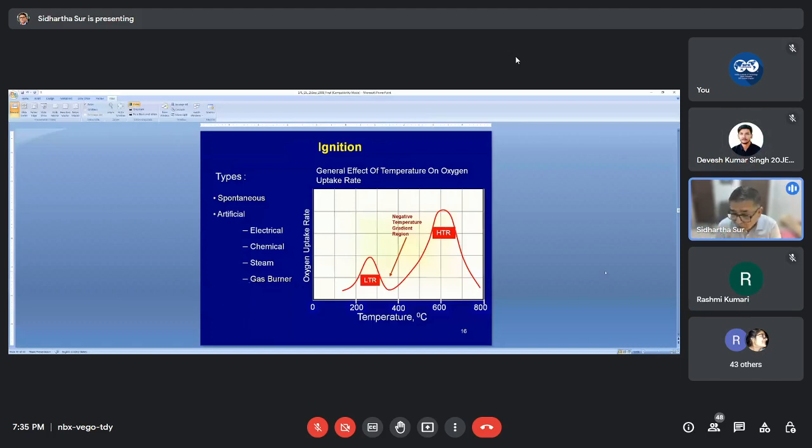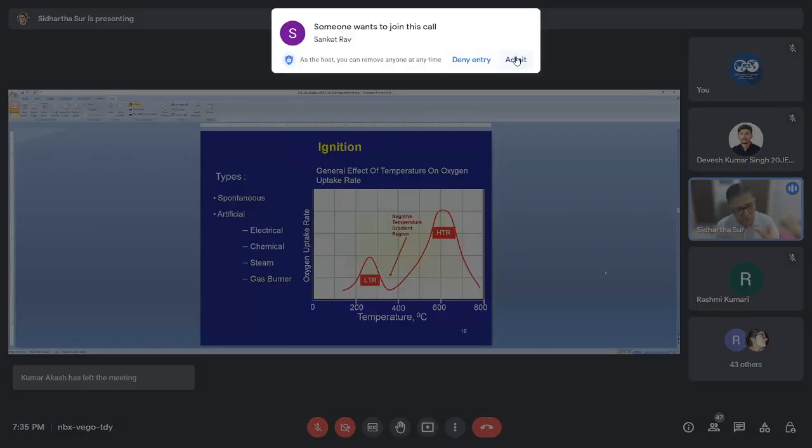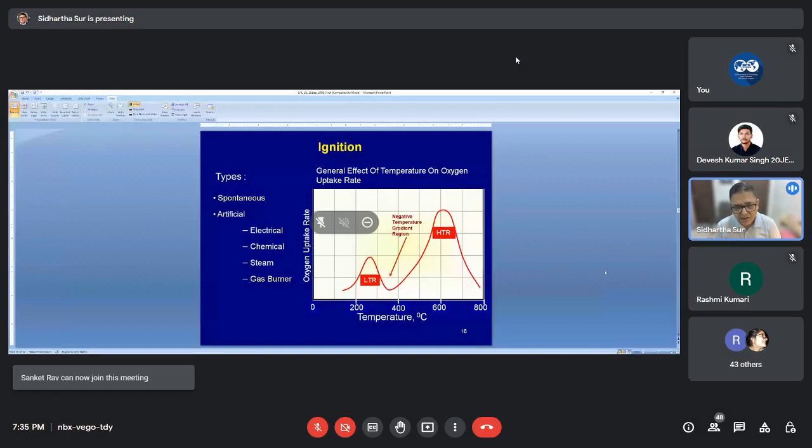In the smaller peak, no carbon dioxide is generated because it is incomplete combustion. Oxygen is getting absorbed into the chain. It is not breaking the chain. So no carbon dioxide, no heat, only a small amount of heat is liberated, and mostly organic compounds are formed which are detrimental for the displacement of oil and enhancement of recovery. So the high peak is the most desirable thing in heavy oil.